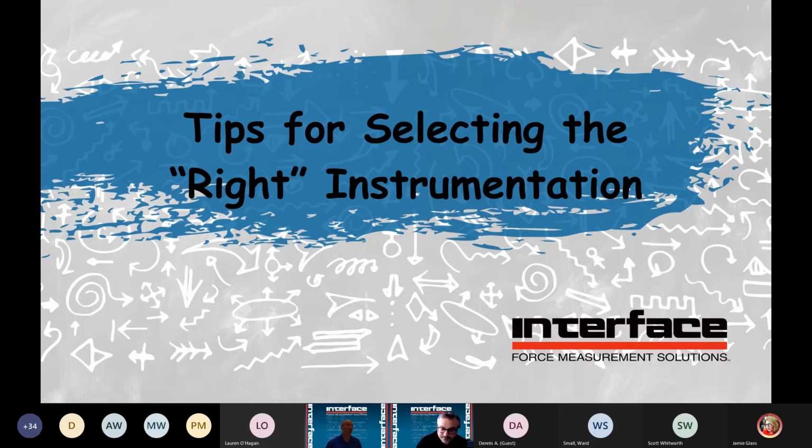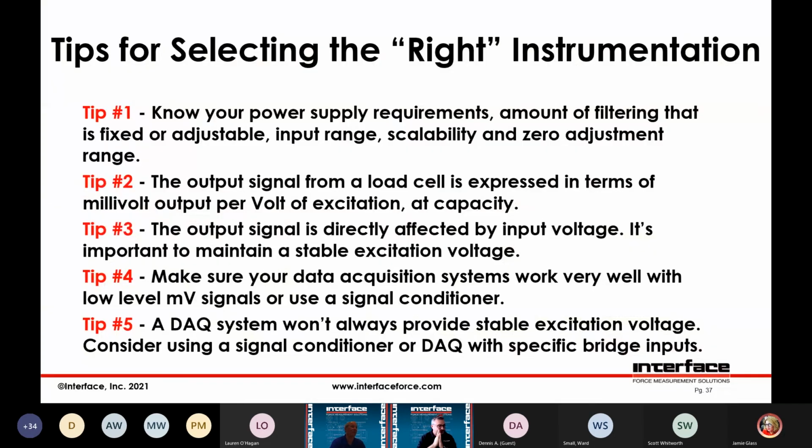We're going to tell you some tips, some things to consider when you pick the right instrumentation. Know your power supply, what kind of filtering you'll need, and what input range. Those are really important in the beginning, as Keith has mentioned. Know that your signal is, in a lot of cases, going to be a very low millivolt per volt signal, and so its output is directly affected by the voltage. So we want to make sure you have a nice stable excitation voltage supplied as you're putting that together.